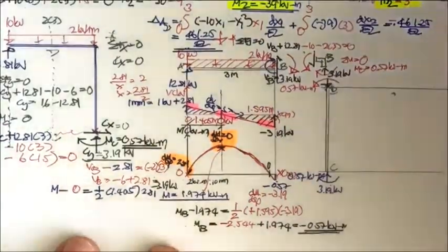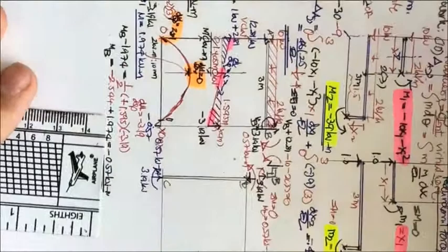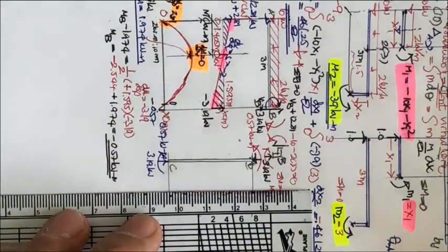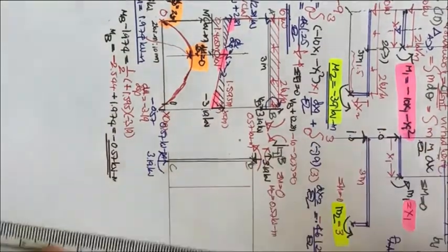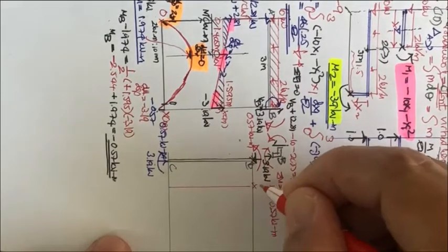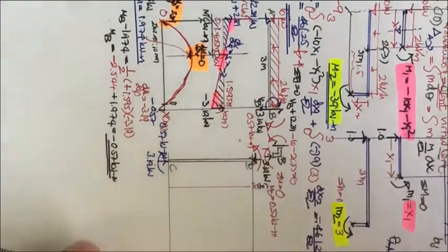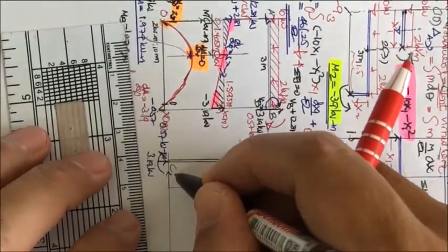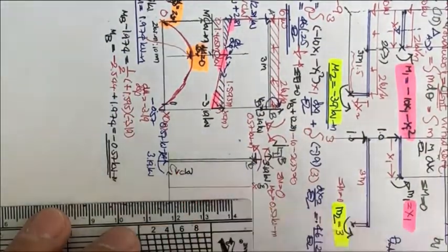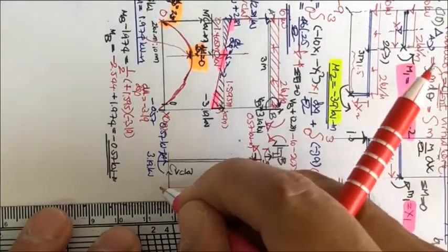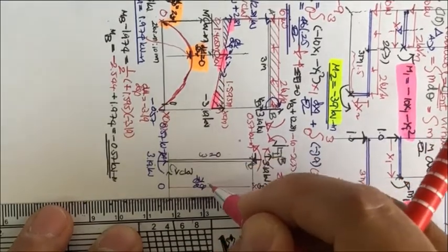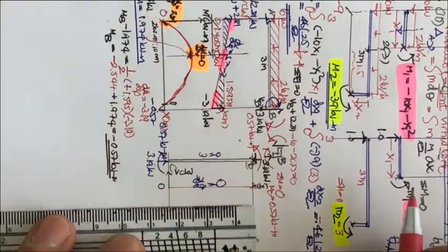Next, we do the shear diagram and moment diagram of the column. Again, you may start by putting this one. Do we have shear here? We have no shear here. This is x, in meters, and then you put the 3 kilonewton. Since there is no shear, this is going to be 0. And dV by dx equals w equals 0, and all are 0.